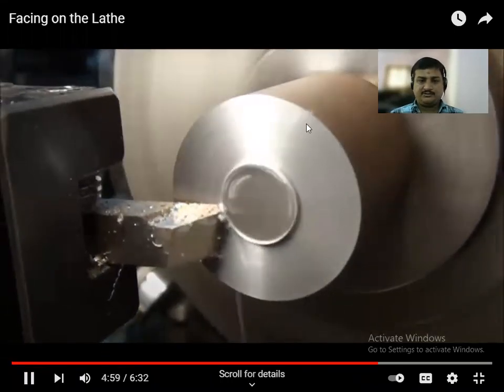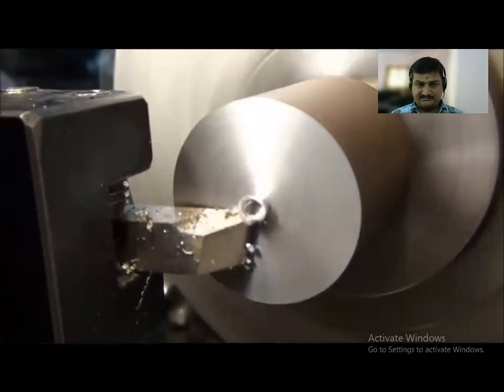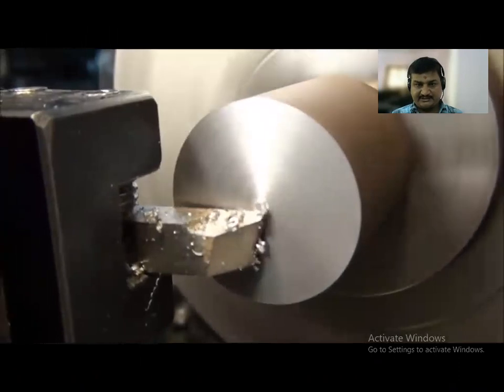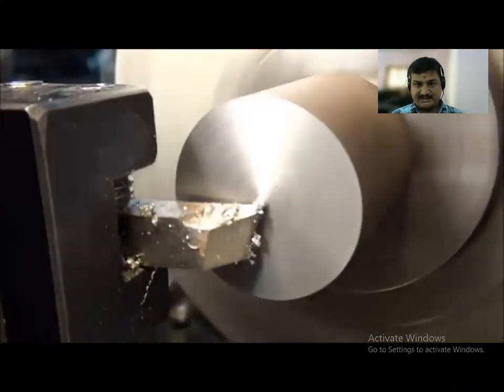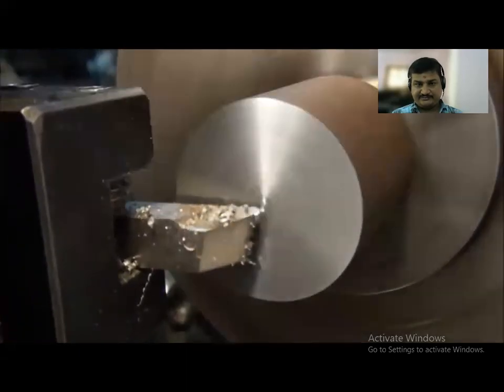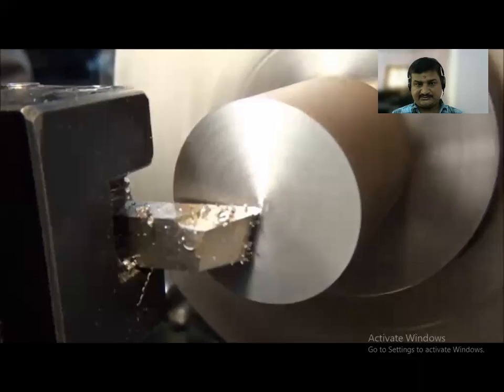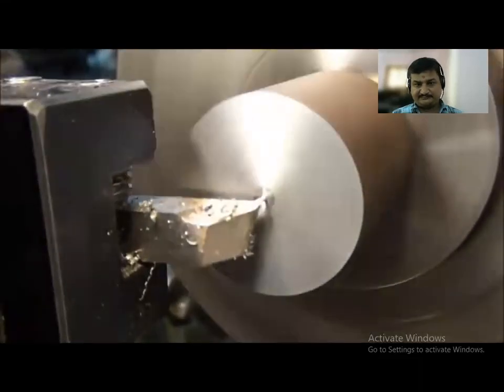Clean out most of that saw cut. Tool is reaching towards center. See, okay, then we can tell how far we are off on center. It looks like we're a little bit low, so let's raise it up a little bit, so we get rid of that little nib of steel left in the center there. A little more.